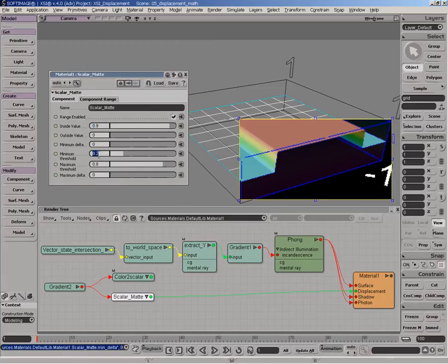So anything that is below 0.2 or greater than 0.8, which is the minimum and maximum, the output will return 0. So I can actually make this value minus 0.9, for example. So now I can have a very interesting displacement map setup with this, and I can actually apply some sort of remapping to be able to do the displacement map mathematics, everything in one shader.